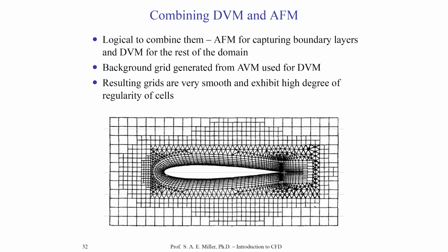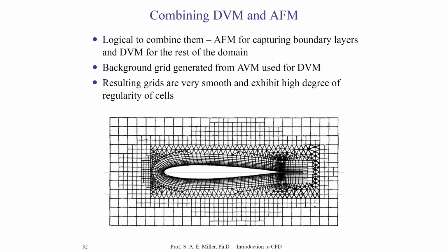They've also put out grid points within the field and gone around them to try and resolve some of the wake of the airfoil, especially in the region of the high shear where the two boundary layers meet. They advance out, and then we have, of course, a new surface, which would be represented in the fluid domain, which is only where the advancing front method was used. Between the advancing front method and the exterior of the domain, we might use another approach like Delaunay Triangulation. In this case, they used a slightly different approach, which we'll talk about next, to fill in the interior of the grid between the advancing front method and the exterior of the domain where the air enters and leaves the computational grid.